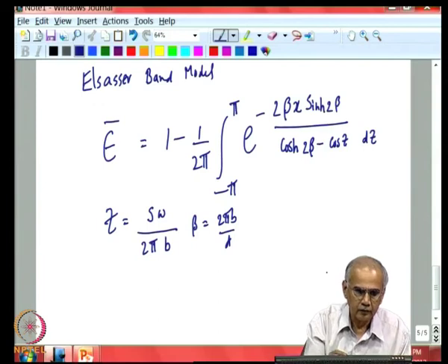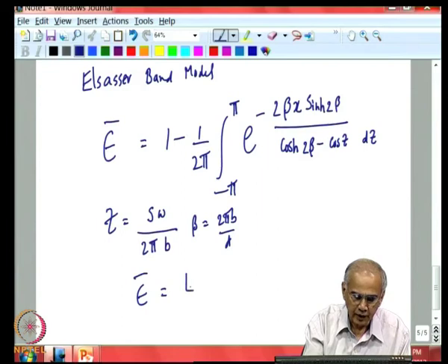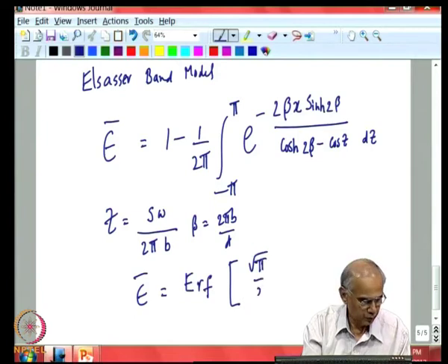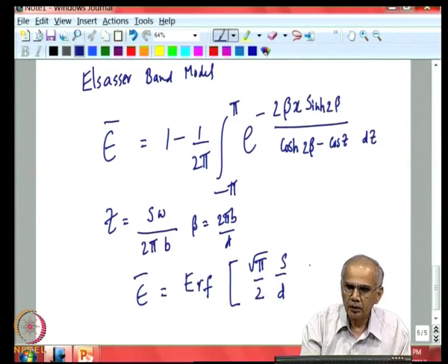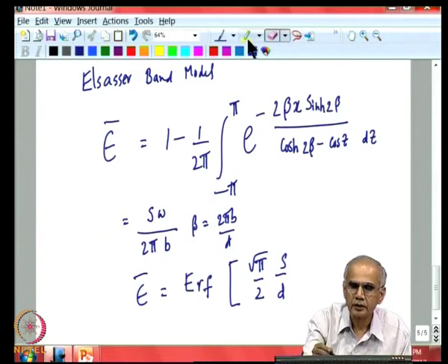One can show from the integration that the emissivity of the Elsasser band is nothing but the error function times root pi by 2 S by d. I am sorry, let me just go back. This is x, I am sorry, this is x here.